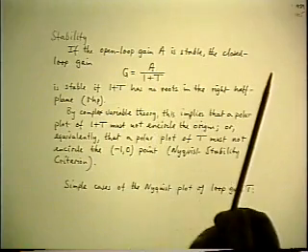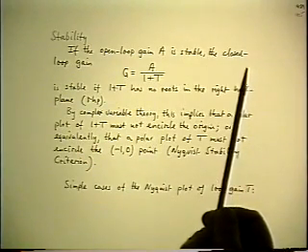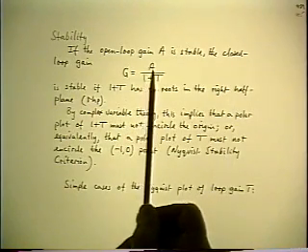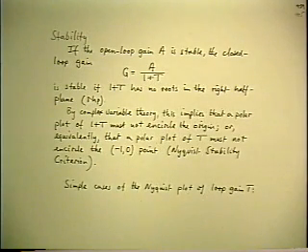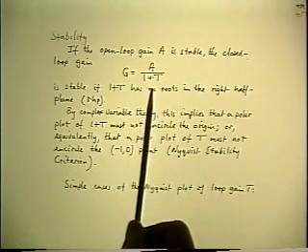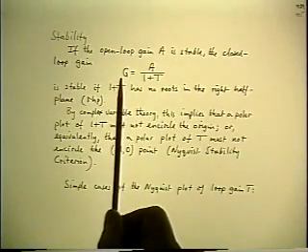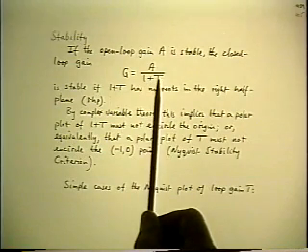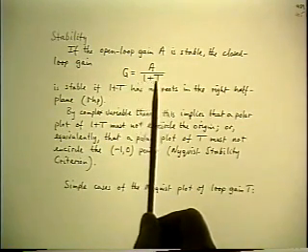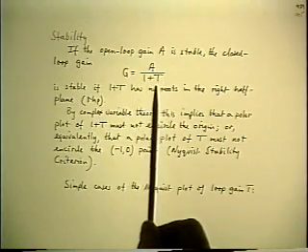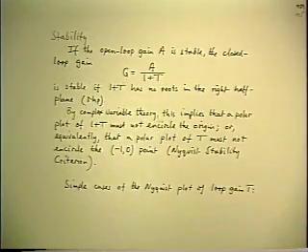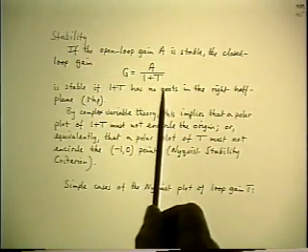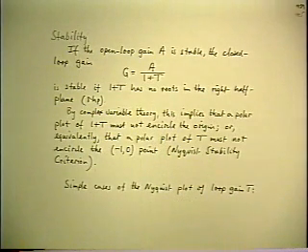So the zeros of A don't matter, whether they're right or left half plane. So if we impose the condition that A itself has only left half plane poles, then we can dispose of A from further consideration. And the only thing left that determines the stability of the closed loop feedback amplifier is the zeros of F. F is 1 plus T. F is in the denominator, so the zeros of F are the poles of G. So the stability requirement is that the roots of F, which are zeros, should all be in the left half of the complex plane.